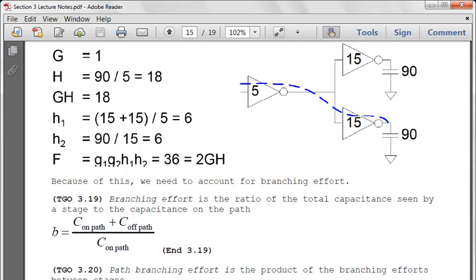And this is where another challenge comes into play. The reason why knowing this is important is because let's say you've designed a cell, and your cell is going to be part of a larger design. You're trying to design an arithmetic logic unit, so you've designed an adder. And your adder is going to be driving a certain number of outputs. You have a sum, you have a carryout. Your carryout's driving the next cell. If you're just designing this, you have to count in order to know the proper delay by knowing the contents of the next cell it's driving.